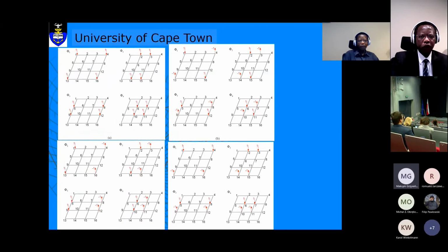So in A, we can see the basis vectors for subspace S1, in B, basis vectors for subspace S2, in C, basis vectors for subspace S3, and in D, basis vectors for subspace S4. After formulating the eigenvalue problem for each subspace, we solve for the eigenvalues and eigenvectors for each subspace and eventually obtain the modes of vibration of the system as follows.